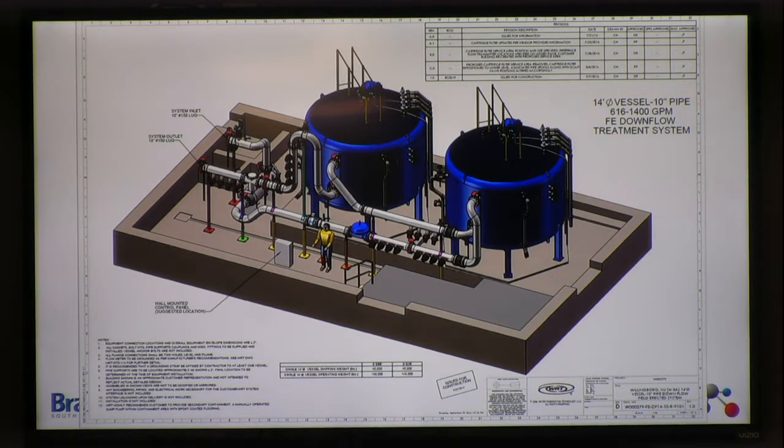And the idea with well 7, since it has the highest radionuclide removal, is to provide a treatment process that removes the radionuclides. Essentially, you come out of here with a near zero value. Only at the end of the cycle does the radium start to creep through. We call it breakthrough. And so they anticipate that and exchange out the media.